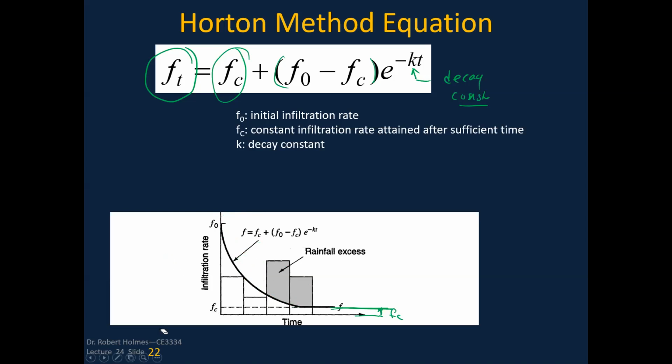Now the problem is, what do you do when you've got rainfall rates that are lower than the actual infiltration rate capacity? That means we've actually got unfulfilled storage in the soil column. And the same thing here. And so there's an adjustment procedure. I've got a bonus lecture that you go through, and you can actually adjust and come up with a new curve that fits in over here. And so this is an adjusted Horton curve. And there's a whole process to do that. And I've got an example in the lecture. I've got the notes on how to do that.